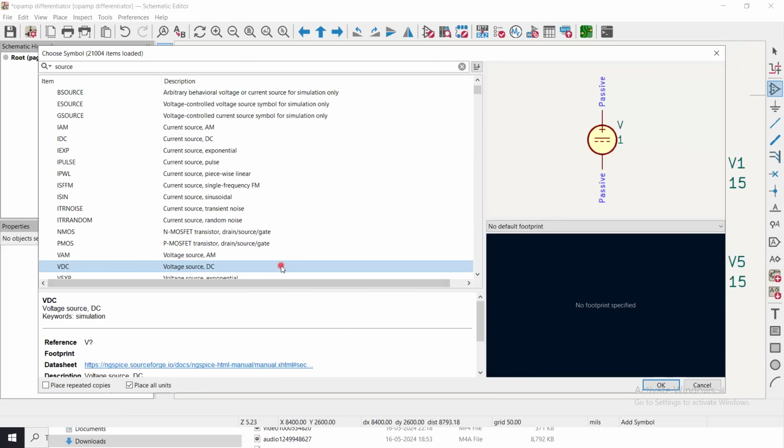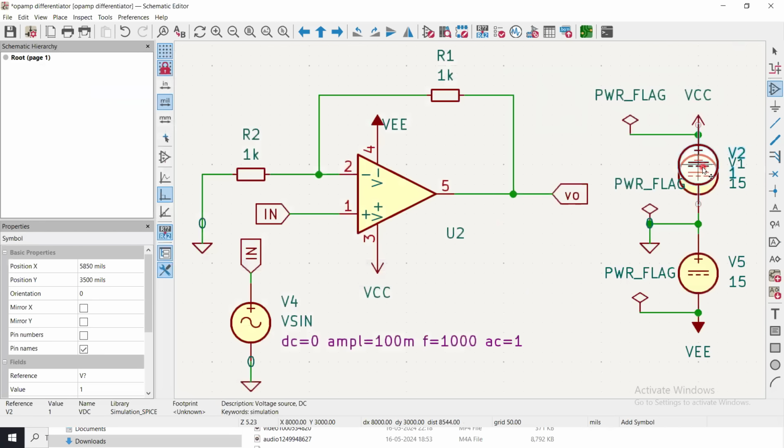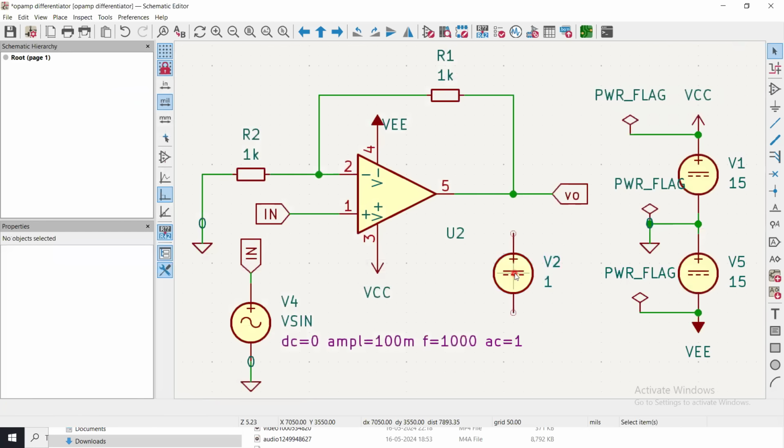After that, I just select and I place one here, I place one here. Okay. And once that is done, I can press escape button on my keypad, then select it again, press delete button on my keypad and get rid of it. So after that, I made the interconnection through the wires. Where is the wire? Here is the add wire. I can simply click here, from here to here, anywhere I want to connect, I can do that. So I have done that. So press escape. Now, what I need is a common ground here, just like here, then I have ground here, then I have ground here.